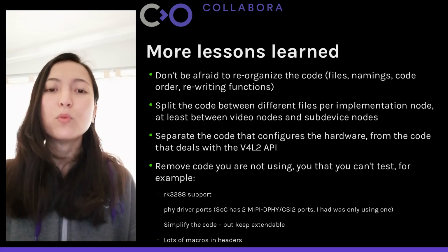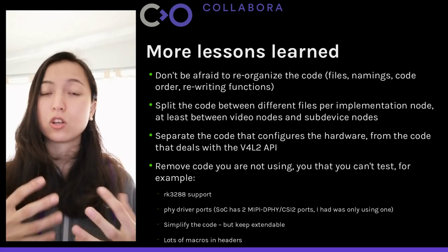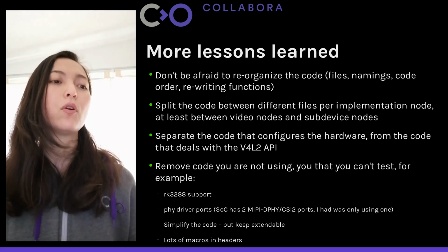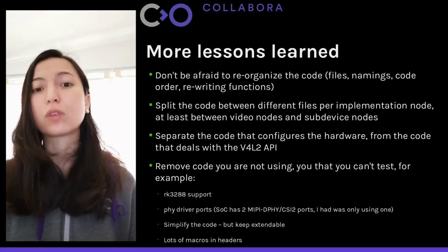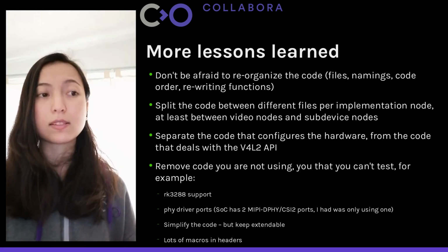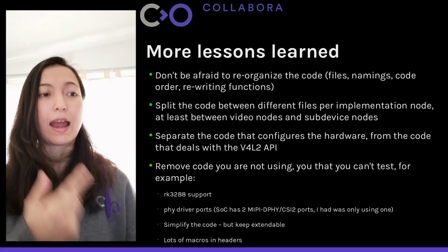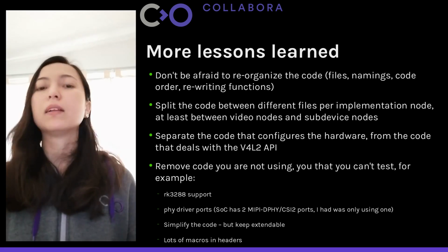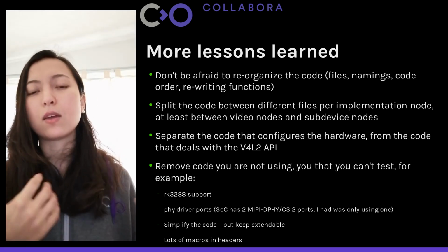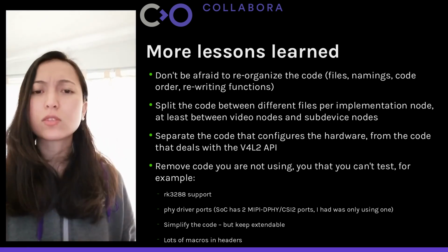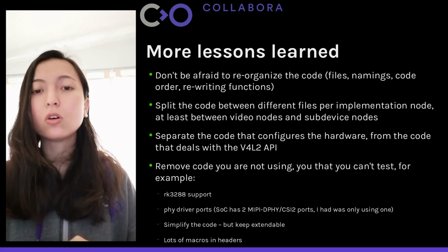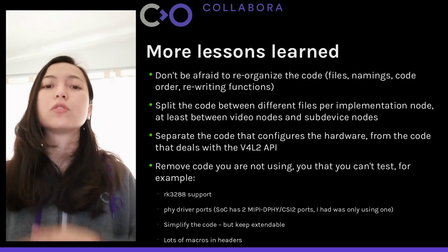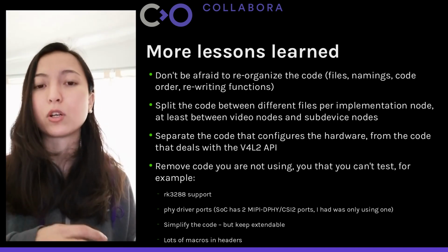Also, I recommend removing all the code that you're not using or that you can't test. For example, the RK ISP1 driver also supports the RK3399 SoC, but I wasn't using it, I wasn't testing it, so just remove it, but keep the code in a way that is extendable. It's easy to put the support back.